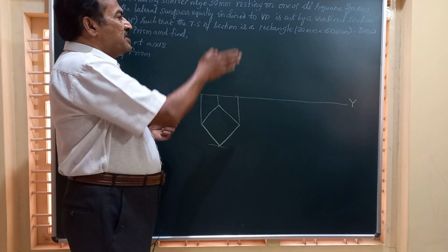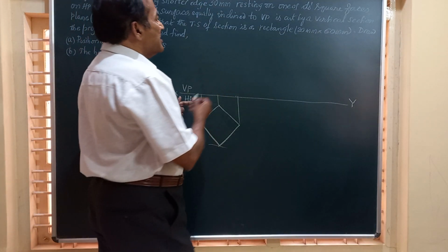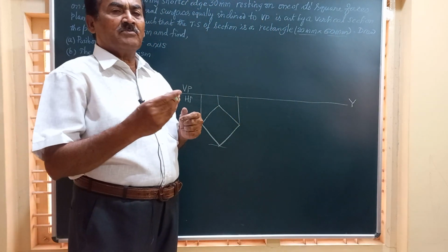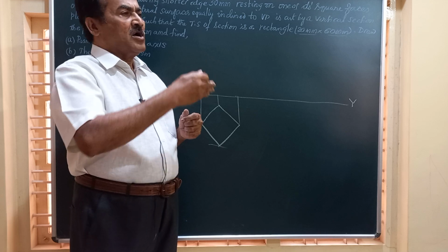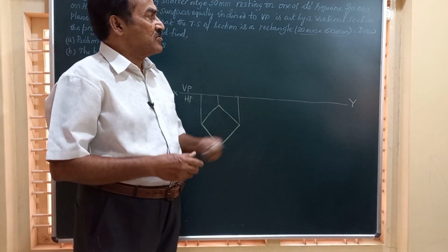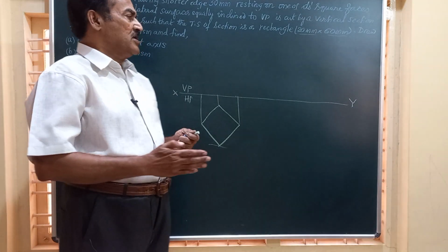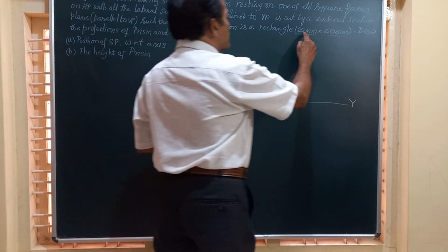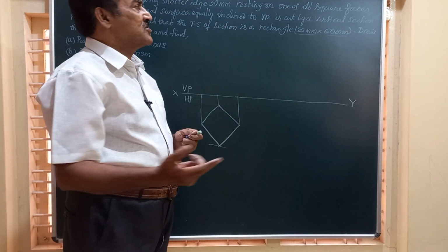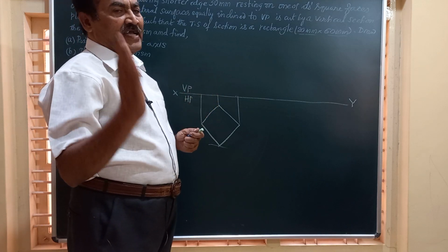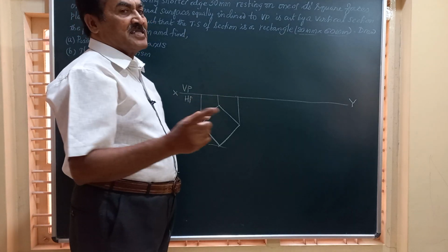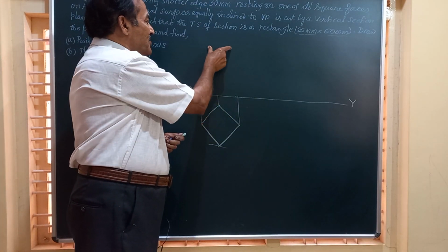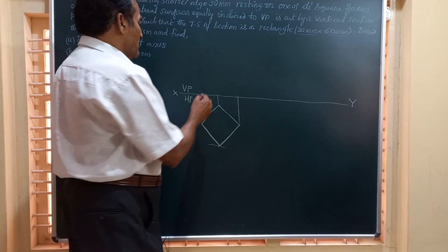Whenever this is cut by a vertical section plane, you get a rectangle 20 mm by 60 mm. So 20 mm is the side, and whatever height they have given you is going to be the height. If it is 80 mm, you get 20 by 80. If it is 100 mm, it is going to be 20 by 100 and so on. Here the height is not specified. You will have to think over and take the height as 60 mm, because only if you have 60 mm height can you have a rectangle 20 by 60. This is a very important concept.